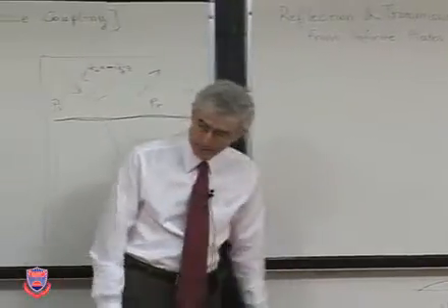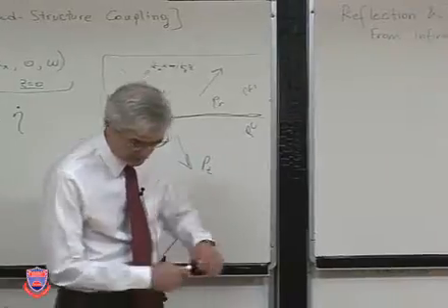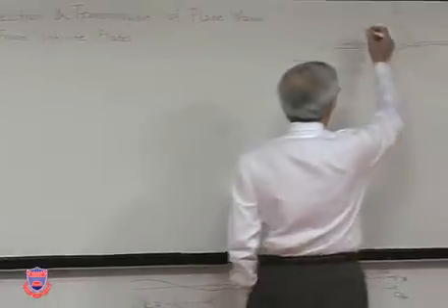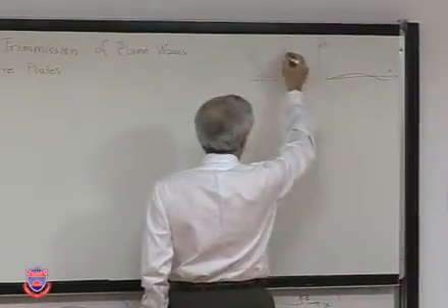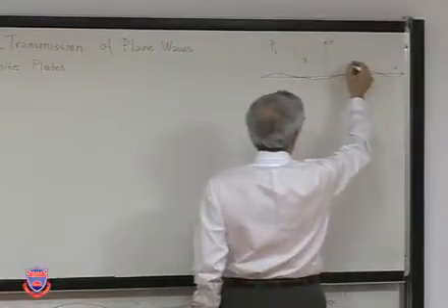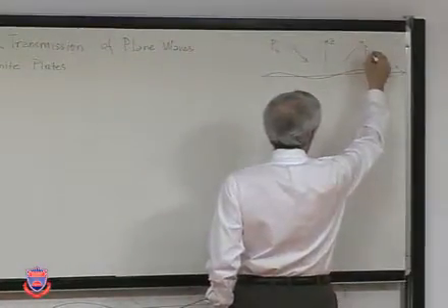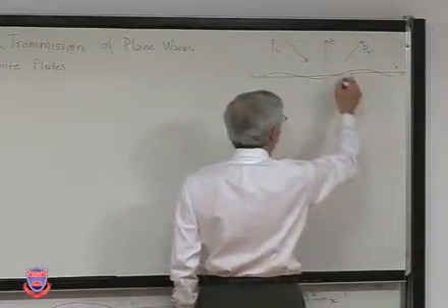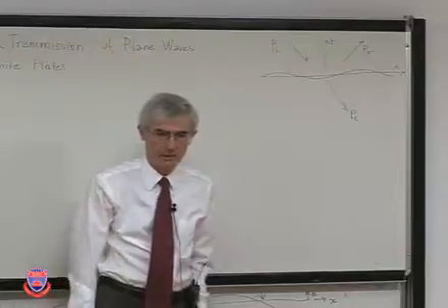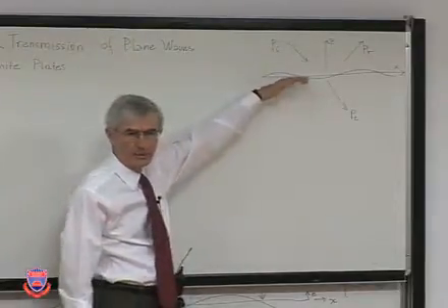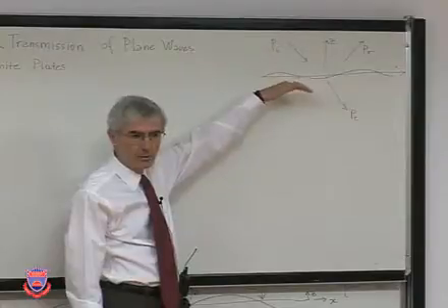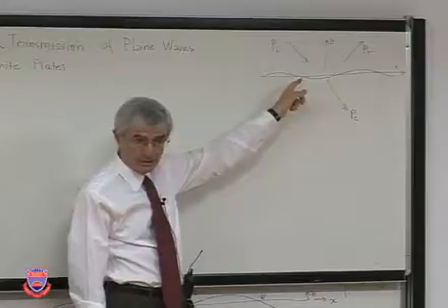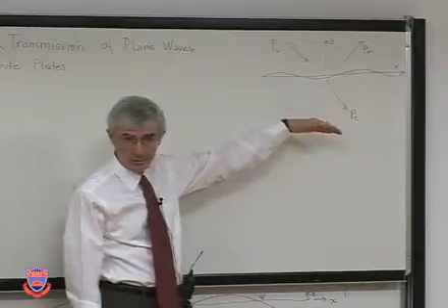First, the standard approach, which is writing the expressions for what we would expect. Incident, and some sound will be reflected, and some sound will be transmitted. What does it mean, sound is transmitted in this case? There's a plate, a metal plate in between. Literally what that means is this sound has to vibrate the plate. Okay? If this plate does not vibrate, there's no transmission.